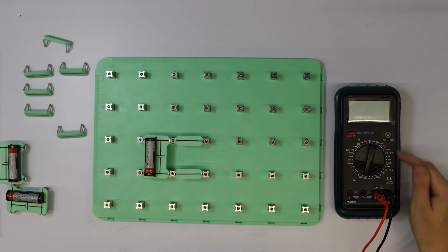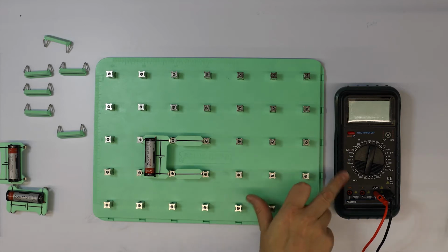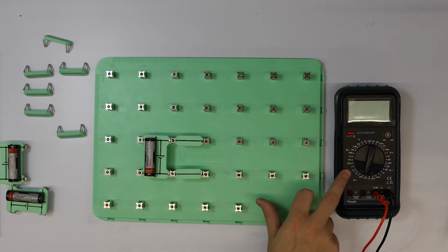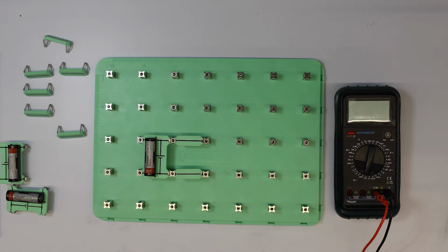One is what's called DC measurements, or direct current measurements, which is where the voltage isn't changing in the circuit, and this is what we'll use today. But later on we'll look at what's called AC circuits, where the voltage actually varies with time, and that's why we need to use this part of the voltmeter here. On the other side we can measure currents, and we'll come on to this in worksheet 2. Down the side here we can measure different current values, and once again we have DC current values here and AC current values here.